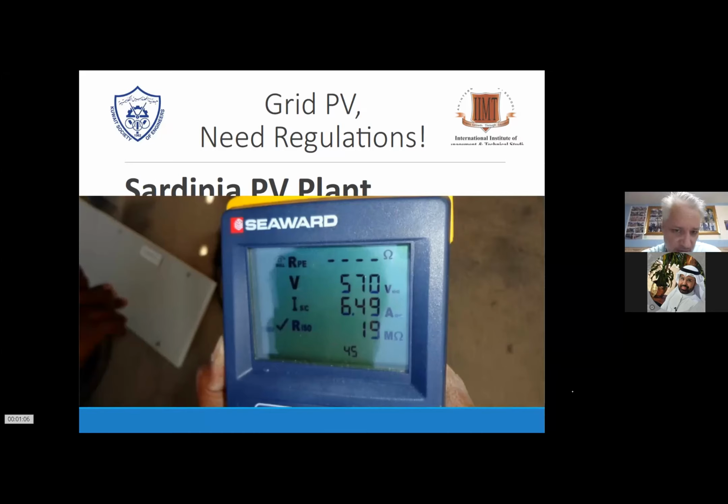So you expect to have these values at the AC side as well. Once you engage and put it back to the system, you want to have an MPPT of a similar value. If it's lower or higher, you either have a mismatch or there's a problem with the other strings. So take the other strings down and see if this single string line will have the same